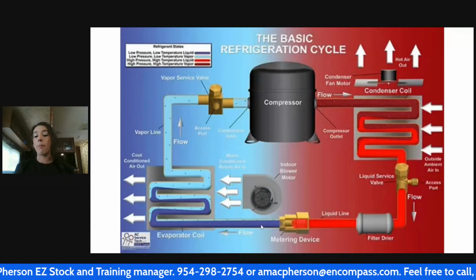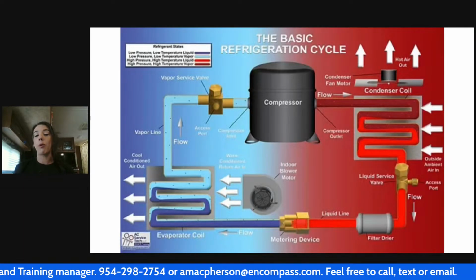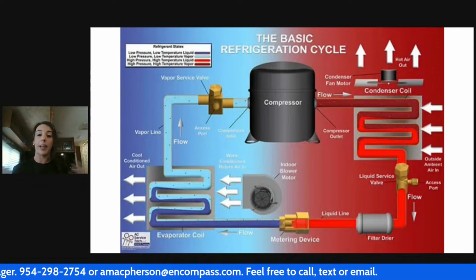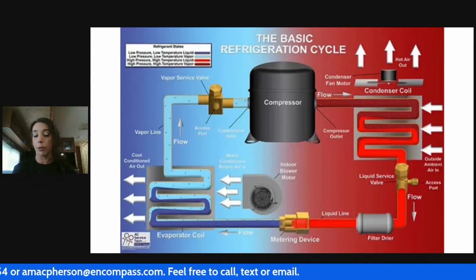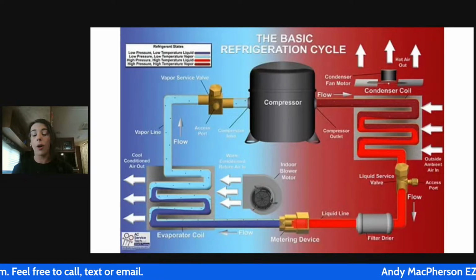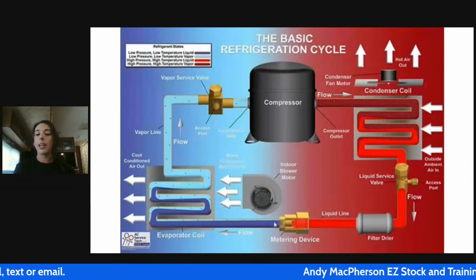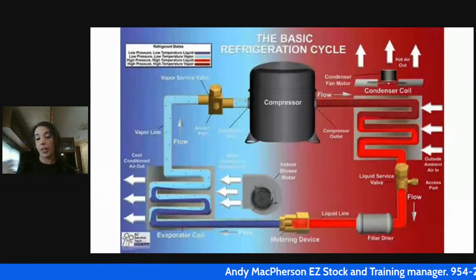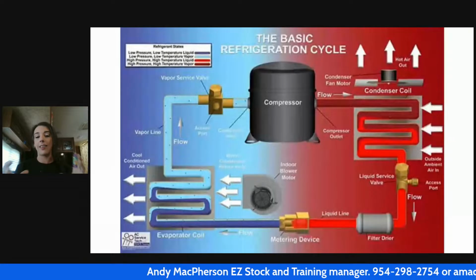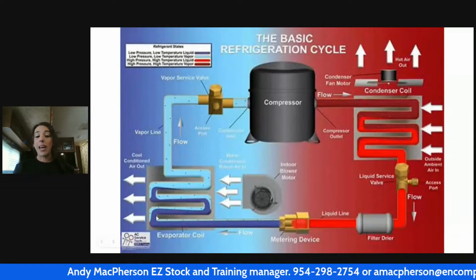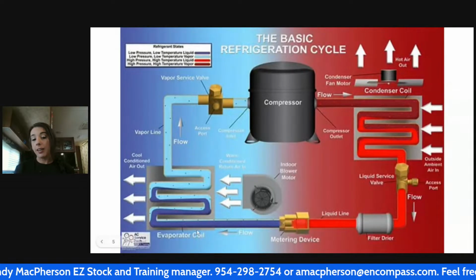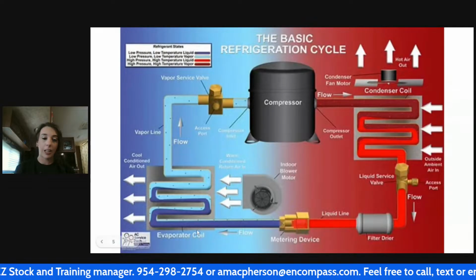And the vapor is just a byproduct, right? Anytime we remove the pressure that quickly, we're going to end up with some vapor because all of those molecules, again, are so hot that they're moving. So a byproduct of metering refrigerant gives us 20% vapor and 80% liquid, basically. It's in that range. So then we enter the evaporator as a 20% vapor, an 80% liquid.